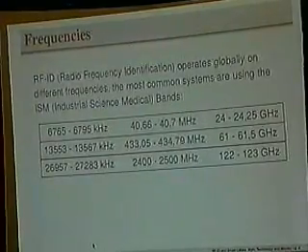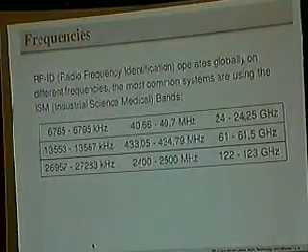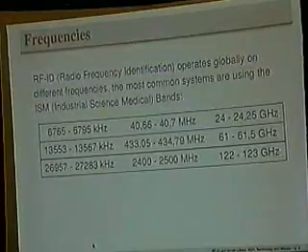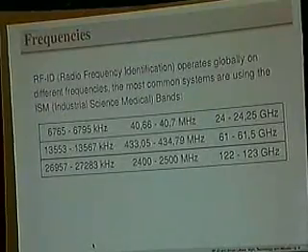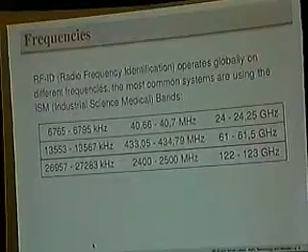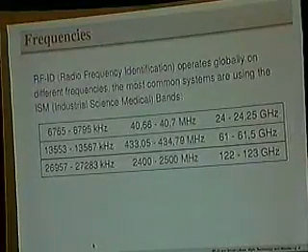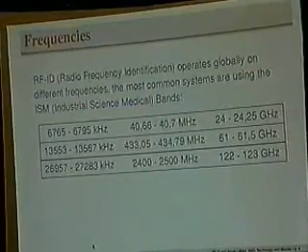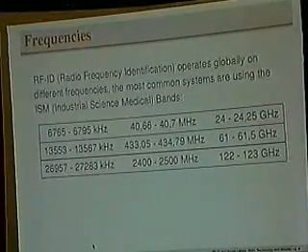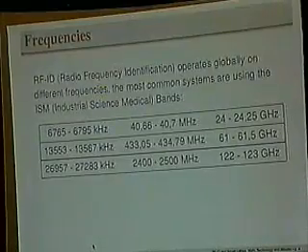What are the typical frequencies for RFID? One of the major problems by detecting and writing with our tool are the different types of RFID, the different encodings, different protocols, and there's a wide branch of frequencies that are used for RFID. We are demonstrating a special frequency area: 13.56 megahertz. Tags that are used at smart labels.